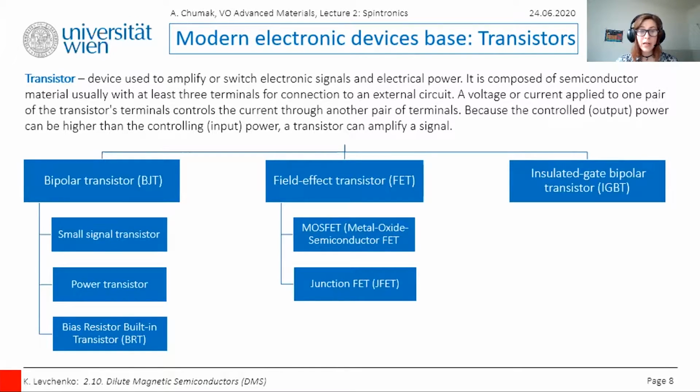We roughly divide transistors into types: bipolar, field effect, and insulated gate bipolar. Bipolar transistors are current-driven devices. Field effect transistors and insulated gate bipolar transistors, or IGBT, are voltage-driven devices. A BJT uses both holes and electrons as charge carriers, unlike unipolar devices like the FET. A bipolar transistor allows a small current injected in one of its terminals, as already mentioned, to control a much larger current flowing through the 2 other terminals, making the device capable of either amplification or switching.